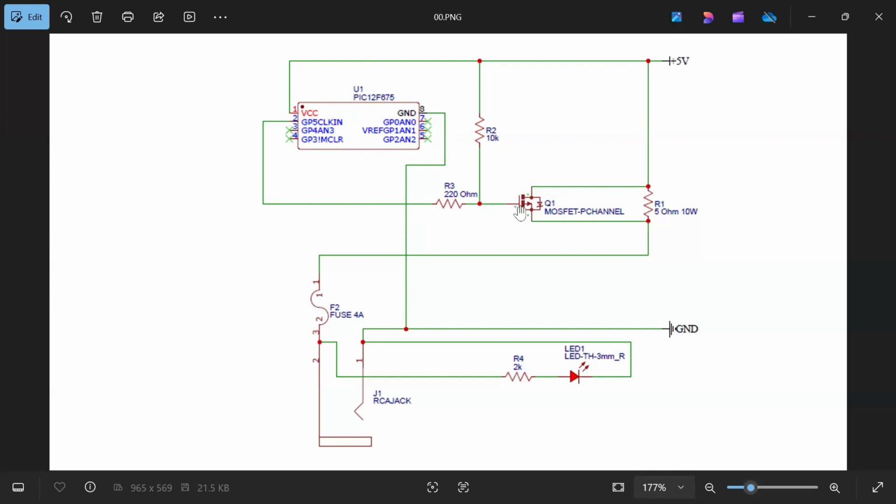Just like we care for capacitor charging, we have to care for the capacitor discharge here, because we need to limit that current so that we do not sink more current into the microcontroller than it can handle. This microcontroller can handle 25 milliamps, and that's how we come up with the 220 ohm resistor here. It's limiting this current to just under 25 milliamps.